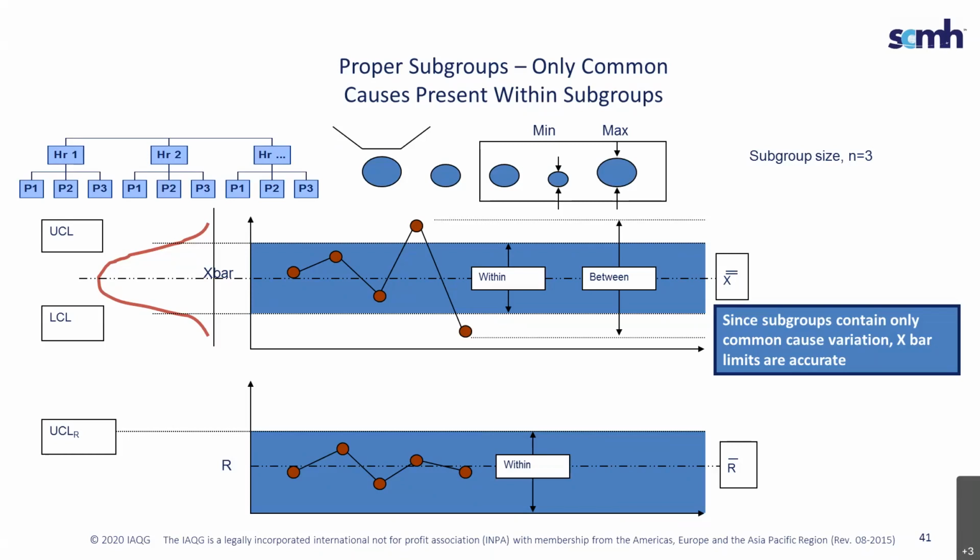The bottom chart is basically looking at the variation that you're seeing within each hour's set of data. So that's an X bar in our chart example. And you can see that by the 4th sample that we took, our parts are starting to exceed the control limits. There's no reference to the spec limits. This is literally just looking at the stability over time.